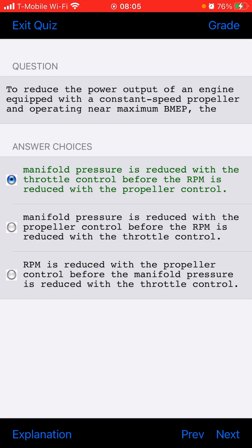Opening at this point allows the low pressure caused by the inertia of exiting exhaust gases to assist in starting the fuel-air mixture flowing into the cylinder. If the intake valve opens too early, some of the burning exhaust gases could flow into the intake manifold and ignite the mixture. This would cause a backfire in the induction system.